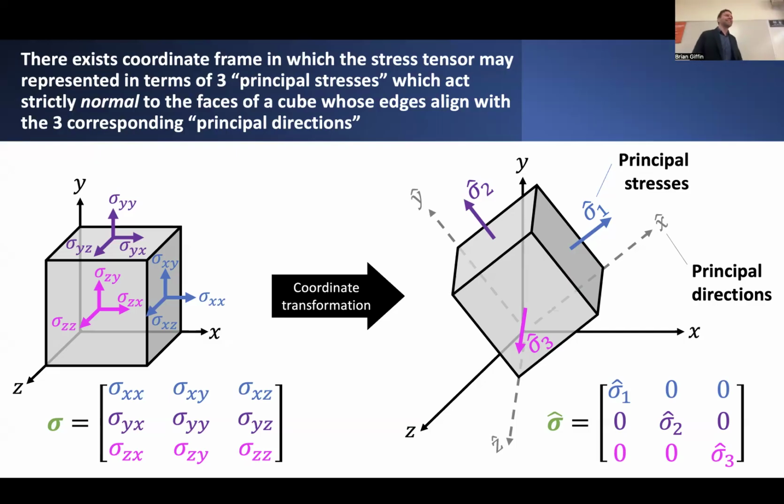And that's pretty fascinating. It basically means that it's always possible to express some generic state of stress that might have shear components of stress in it into this format, which looks like there are no components of shear stress acting in it. Now, that doesn't necessarily mean that there is no shearing going on. Certainly, it just depends on how you've chosen to define your coordinate system.